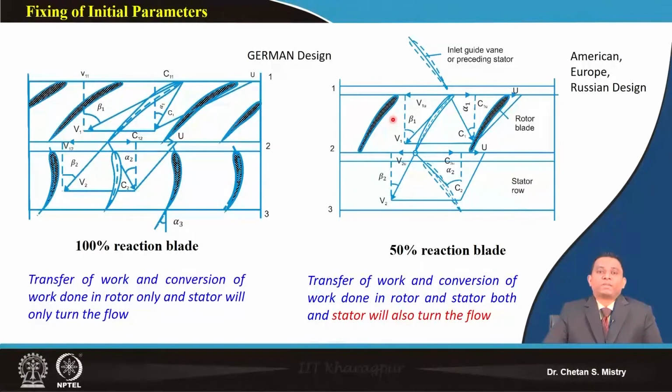Okay, we have realized that part. We have discussed this issue many times. So what will happen if I have my delta beta large near the hub region? There may be chances of my flow getting separated in that region. And in order to address this issue, it demands that inlet guide vanes need to be incorporated.